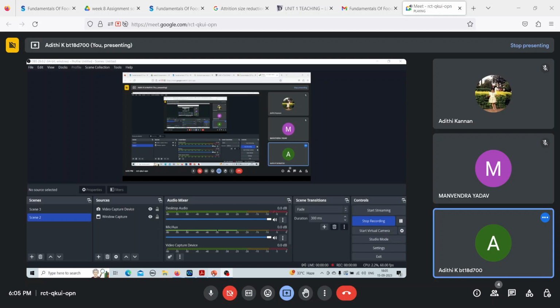Since this is pretty difficult to remember, there is a generalized formula for this. Let's say you have d_q,p, and let's say this is the notation for a particular diameter. For that, the generalized formula is summation of d raised to q into n divided by summation of d raised to p into n. First we need to see what q and p are. We know d is the diameter, we know n is the number of particles, but we do not know what q or p is. So q or p depends upon what is being asked in the question.